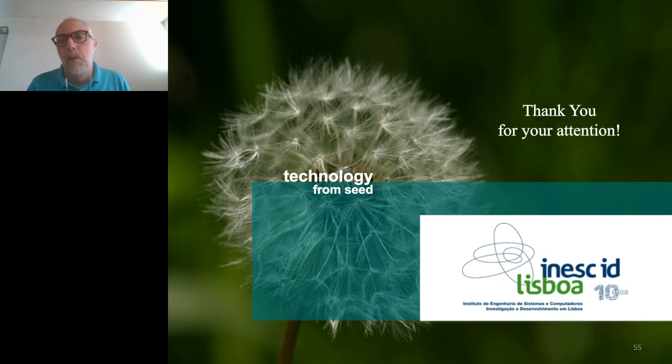If you ask about my group, what we have been doing more and more is using HLS, because we want to evaluate the impact of this type of unconventional system in new emergent technology by simulating, or in traditional technologies but using current architecture. In both cases, we would like to know exactly what the improvement is by using this type of unconventional arithmetic. So we move more and more to high-level synthesis, but we have to be careful, because when you describe the arithmetic, you have to put inline in your description the arithmetic units that you have.